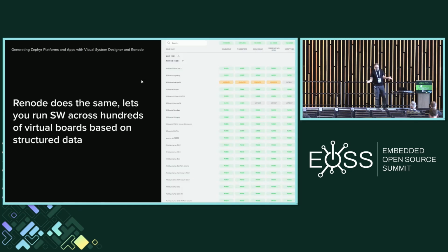And we are also developing a tool called Renode, which gives you the ability to simulate systems. Now, to simulate systems efficiently, of course, you have to model them. That's something you can't avoid. So you have the device. You normally write a driver to make your SPI peripheral run. On the other side, you'll have to build a model, and that model will have to describe what this SPI peripheral is doing. So there's non-negligible work involved in doing that.